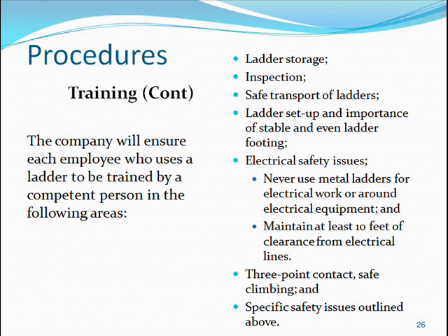Ladder storage, inspection, safe transport of ladders, ladder setup and the importance of stable and even ladder footing, electrical safety issues, never use metal ladders for electrical work around electrical equipment, and maintain at least 10 feet of clearance from electrical lines, 3-point contact, safe climbing, and specific safety issues outlined above.